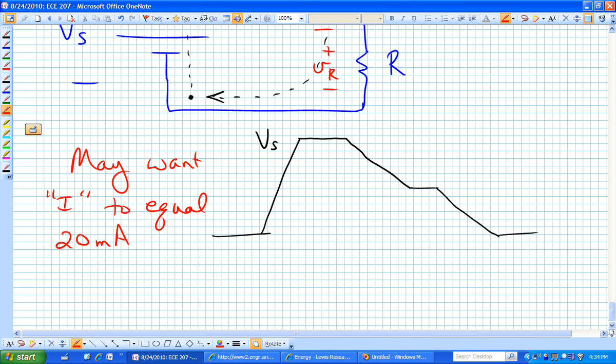Typically in the past they were always red. Now you've got all sorts of LEDs that you can have. But it might be that for this particular LED it might be really efficient, maybe it only needs 10 milliamps of current flowing through it to make it look bright. If the LED says 20 milliamps, you don't want to be throwing 50 milliamps through it. It'll probably not last very long, or it may burn up right away. Another way of writing 20 milliamps is 20 times 10 to the minus 3, or 0.02 amps.